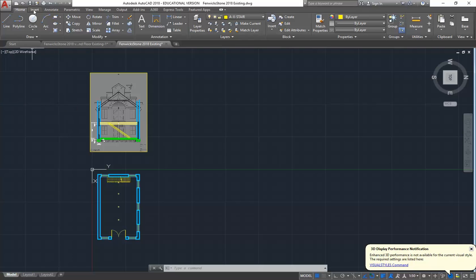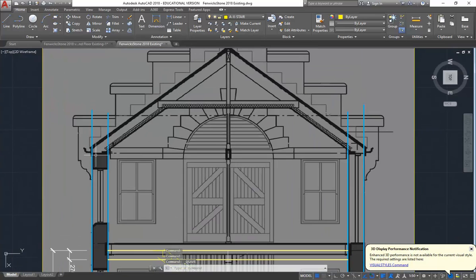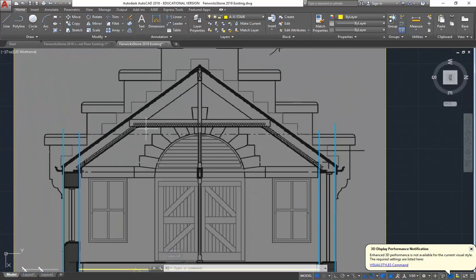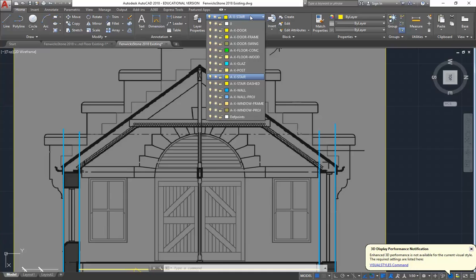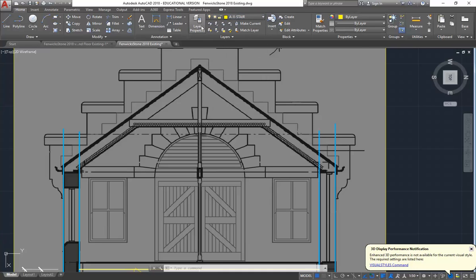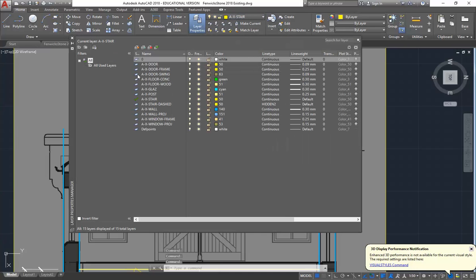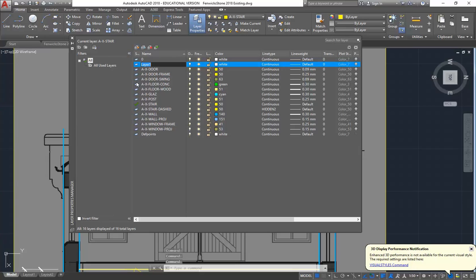Okay, so now that I've got the image inserted, I can continue drawing, particularly the roof elements. And I know most of you have done a good job actually with that. So I'll just maybe very quickly set out an outline so I can show you how to project this at 90 degrees. So I'm going to make a layer called A Roof